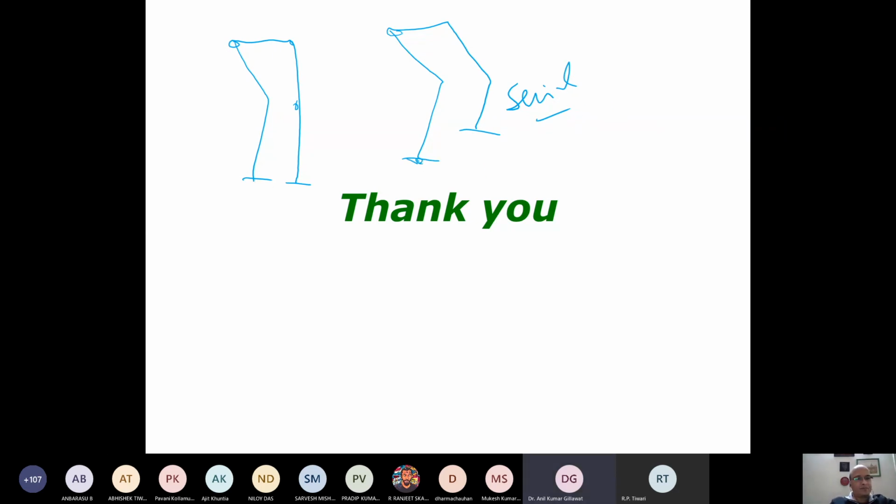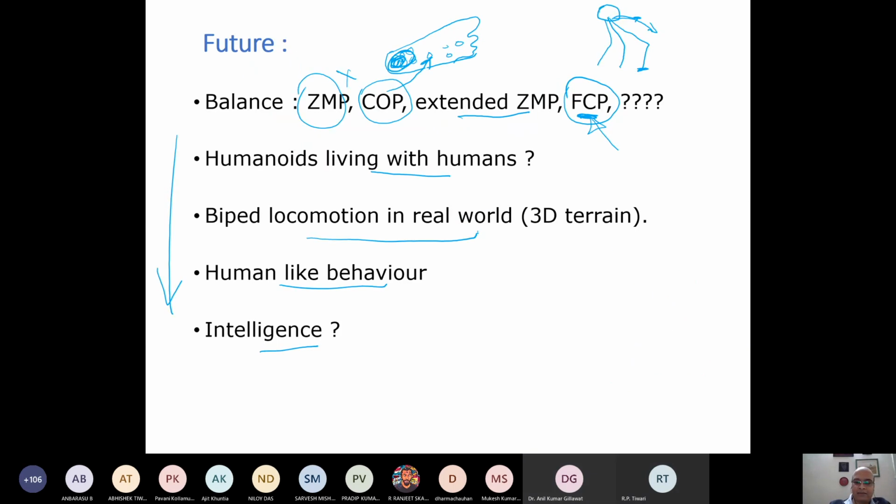And sir, you were talking in the last lecture about the Newton-Euler method, and that you find out that relation between the ith link and I+1 link. Can we use it for defining velocities and position analysis also? Yes, because in the Newton-Euler or Lagrangian-Euler, your input is your joint velocities, right? Joint position, and the derivative will be the joint velocity. So you have to define that, and that actually comes from the trajectory. I did not say it here, but yeah.